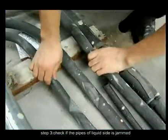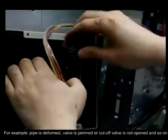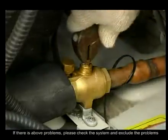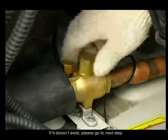Step 3. Check if the pipes of the liquid side are jammed. For example, a pipe is deformed, a valve is jammed, or a cutoff valve is not opened, and so on. If there are the above problems, please check the system and exclude the problems. If they don't exist, please go to the next step.